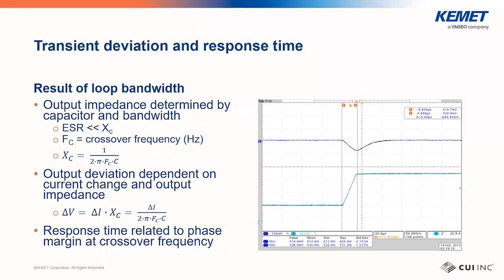The response time, on the other hand, is controlled by something called the phase margin. It relates to the dampening factor of the step response. An underdamped response will be fast, but will overshoot and can oscillate. An overdamped response will be slow, but will not overshoot. And a critically damped system is right in the middle, achieving a fast response without overshoot or oscillation. A phase margin of around 60 degrees gives close to a critically damped response. A lower margin will become less damped, and more margin will tend towards overdamping.